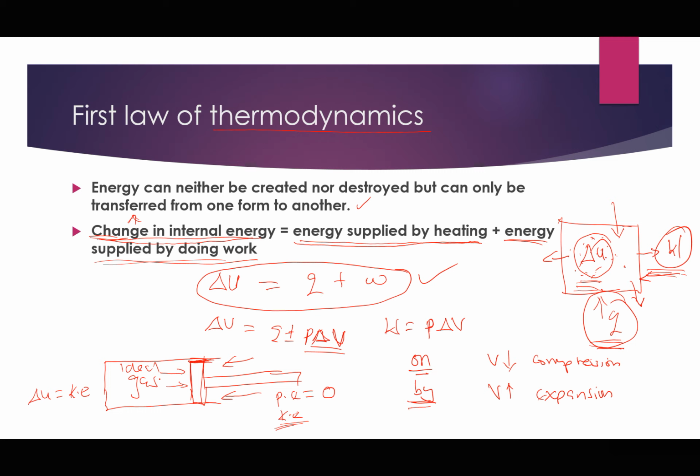So in both cases, whether we are heating the gas or whether we are compressing the gas, we are adding energy to the system. And by conservation of energy, this energy cannot just disappear. It must be transformed to another form or another type of energy. Therefore, the energy which is the work done in pushing the piston will appear as a change in internal energy of the gas. The energy we apply by heating will end up as an increase in internal energy of the gas.